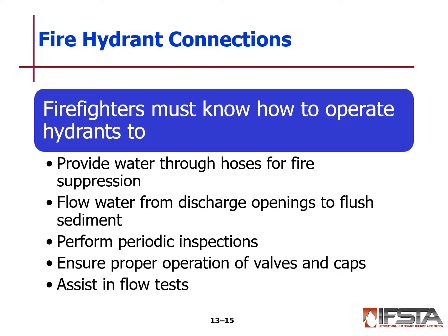All right, fire hydrant connections. As firefighters, we got to know how to operate our hydrants. Our goal is to provide water through hoses for fire suppression. We flow water from discharge openings to flush sediment out. So when we go to hook up to this hydrant, we get the cap off. We want to crack that open real quick, flow some water, get any sediment or trash out.